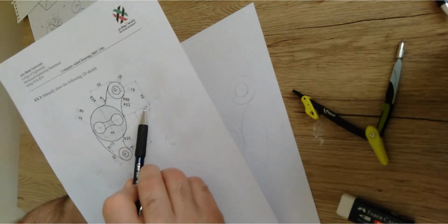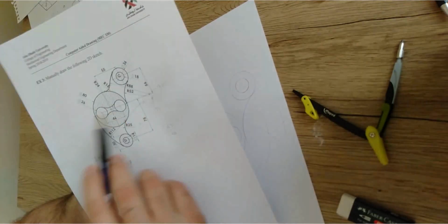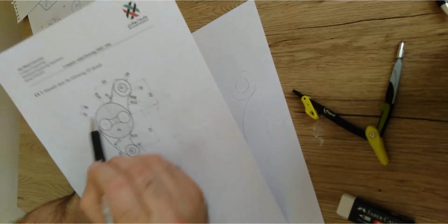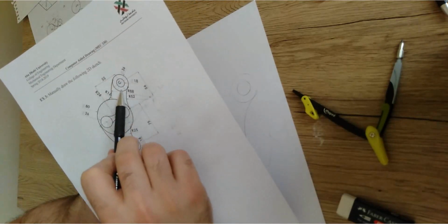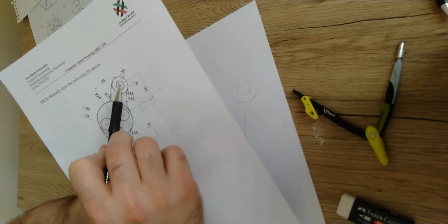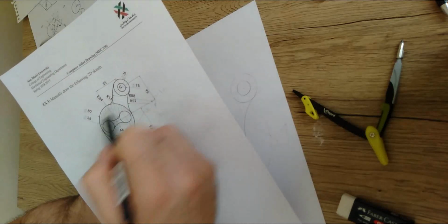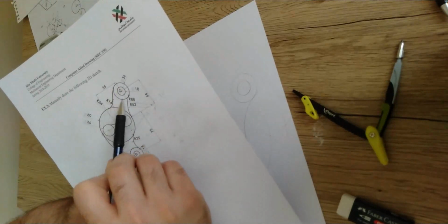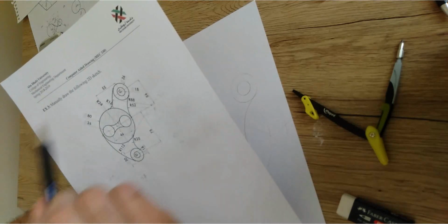So how can we locate this center point? This is the tricky part, right? Basically this curve R88 is tangent to this circle, and it is tangent on the other side, but this other side we don't have. So what I'm going to do is use the center of this circle that is already there for the first tangency. From this center, I'm going to draw an arc. This arc is going to intersect with the center line to locate the center point of this curve R88. So again, to draw the R88, we're going to use the center of this circle. Why the center of this circle? Because the R88 is tangent to this circle, so I'm going to use its center.